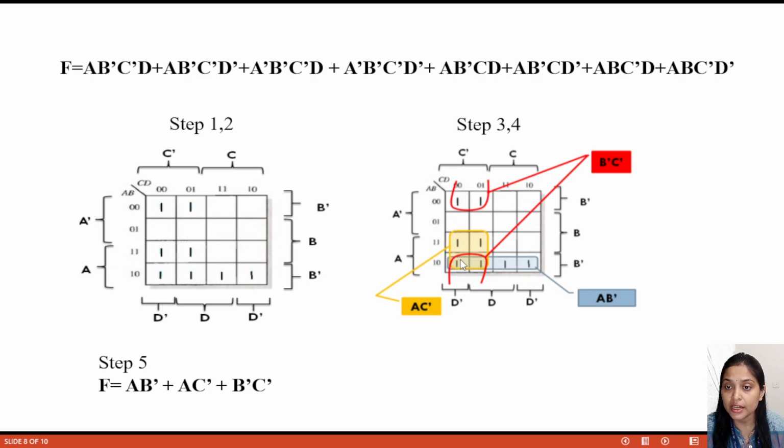So here it shows, it actually shares 2 rows and 2 columns. So we have to choose which one we have to cancel. From these 2 columns we can cancel d, because d is in the form of 0 and 1, so c bar will come from here. And in these 2 rows we can cancel the b component because b is in the form of 1 and 0, so we only consider a and c bar, a and c bar.